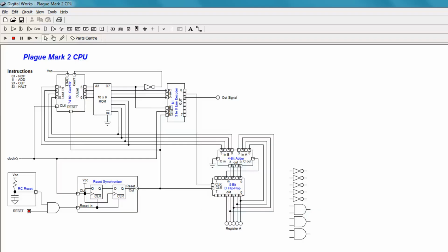I consider that 5th output from register A to be an internal carry flag, and not actually part of register A. We could connect the carry flag to the carry input of the adder, but I'm not going to do that. Instead, I'll make use of the carry flag a little later. In the meantime, we can still use it to see a 5th bit of a summed output. So now, with this slight modification, we can add a series of 4-bit numbers together.